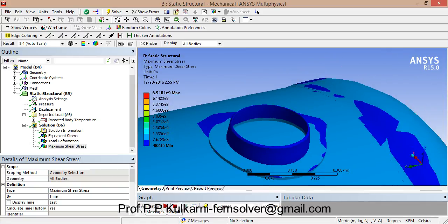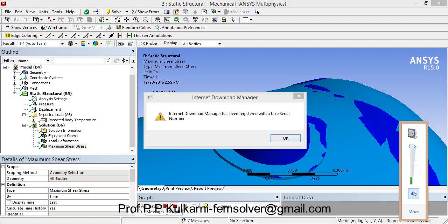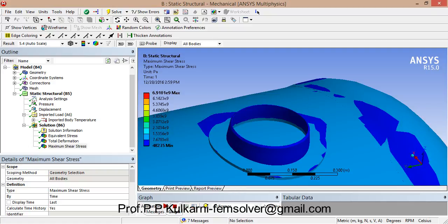localized stresses are occurring. Are you getting? Because here are chances of leakages. Therefore, localized stresses occur in this region. So you have to select this region for finding out localized stresses. Are you getting? So we will find out localized stresses around this area. So we will select mesh and lasso select. We will select lasso. You select the region around this.